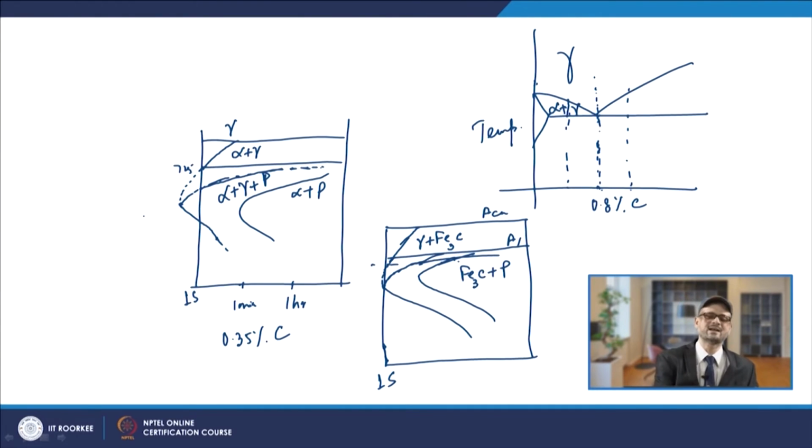So, in this case it can be seen that hardenability is less. Your chances of conversion to martensite become less, because you will have to apply a very high cooling rate, and then only you will get the whole martensite. Now, how to change this hardenability? Basically, with the use of alloying elements you can very well change the hardenability, and you can have the conversion to full martensite structure.